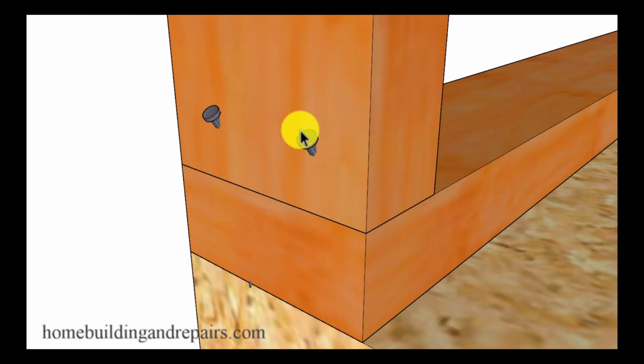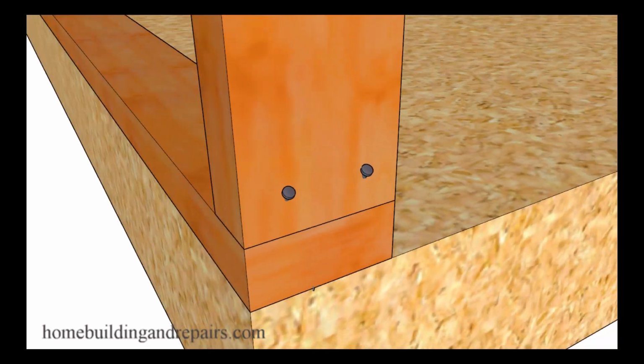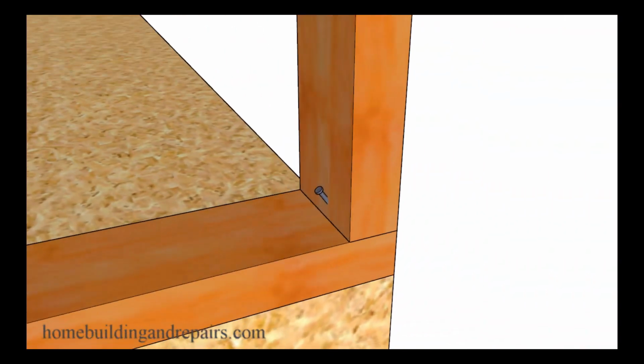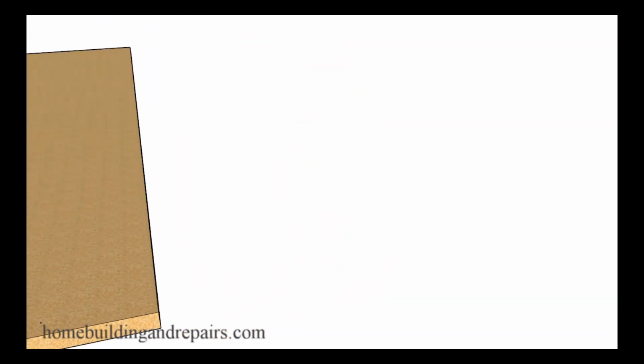Next up, let's take a look at how the wall framing studs might be attached to the framing plates. And that would be with 2 16D nails on one side and 1 16D nail on the other side. And when I first started, this method right here was the preferred method on most of the architectural building plans. However, it was rarely used.